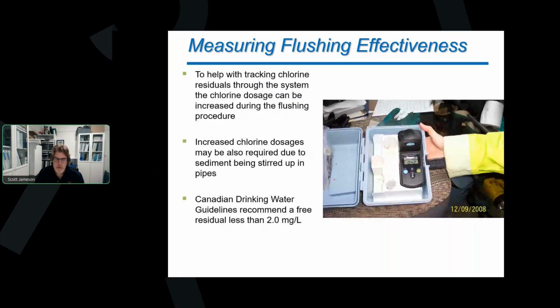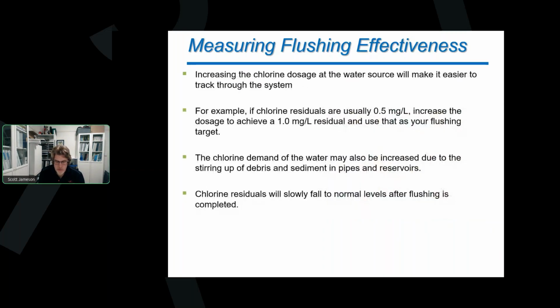Chlorine residuals, right? Again, we should see those chlorine residuals come up after we finish the flushing program. So we want to measure those pre and post flushing, record those values. It is also a recommendation that before you start your flushing, you might want to increase the chlorine dosage that you have going into the system. Right? This does a couple of things for you.